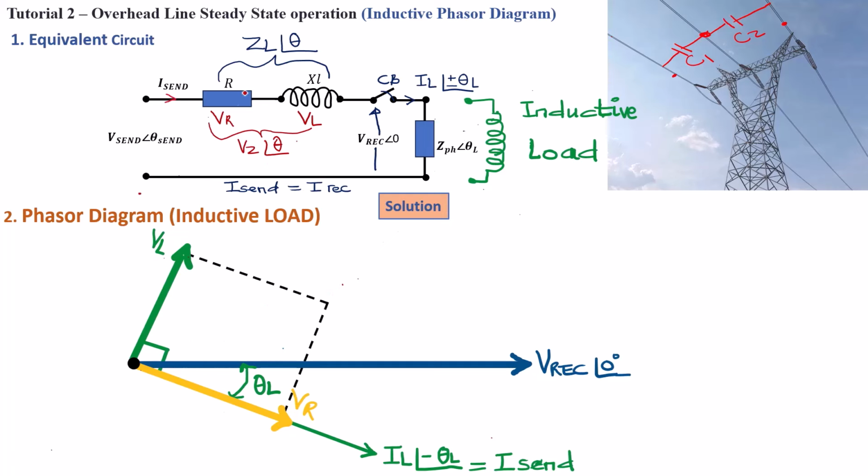Equally, if we know the value of VR and the value of VL, we can calculate the value of Vz, with its angle, and plot the Vz phasor in reference to the V receiving end, because it is important to note that Vz is the voltage drop on the transmission line that is in reference to the receiving end voltage.